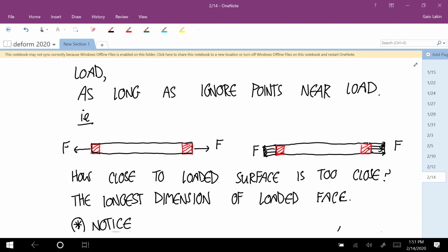Okay, so we did the truss calculation, talked about how to translate that back to stresses. Once you're at stresses, you can calculate strains, you can do principal stresses, max shear. Yep. If you have two of the same minimum stresses, like in this case, like 5, 0, 0. Can you use either for the middle? Yes, exactly. Yep, either one. And so what that says in the case of a bone is it could fracture 45 degrees this way, looking at me, or it could fracture at 45 degrees looking from the side. And that makes sense. Any other questions? Okay, that's all.